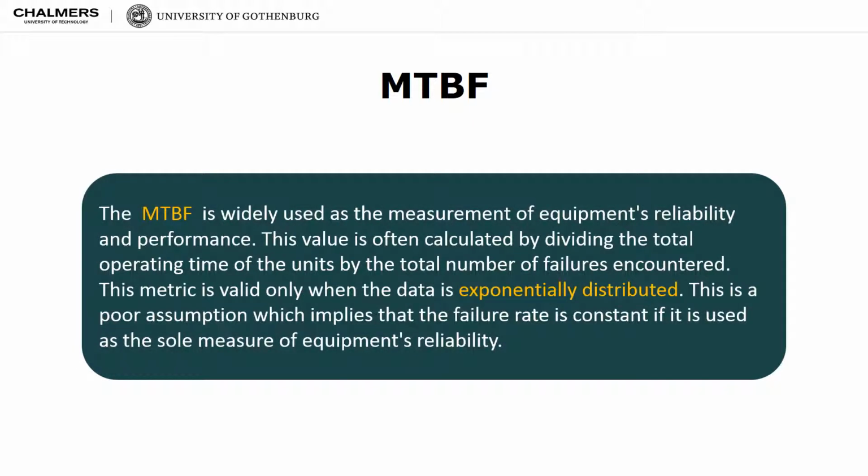The MTBF is widely used as a measurement of an equipment's reliability and performance. This value is often calculated by dividing the total operating time of the units by the total number of failures encountered. This metric is valid only when data is distributed exponentially. So when you apply it, you should really check it. In many cases, it's a realistic assumption, but you should check it.